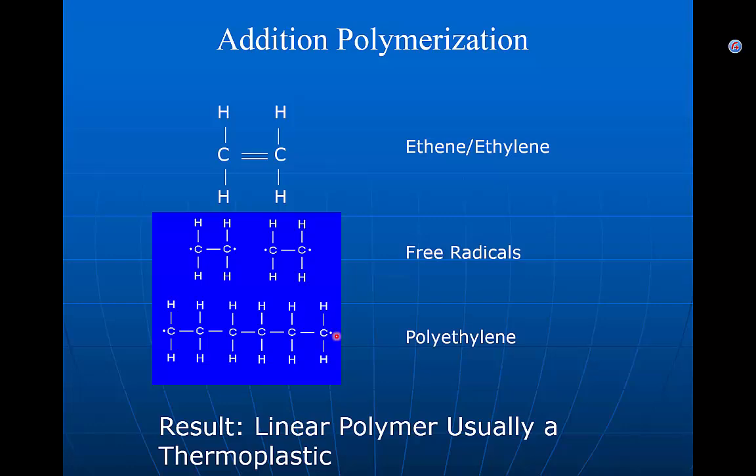Now, addition polymerization is favored particularly for biological materials, where it's going to go into the body or be used in a biological environment, because this process tends to produce a very clean material. If it can be done in the gas phase and you have no solvents present, no water present, you're simply going to have polyethylene and nothing else added.